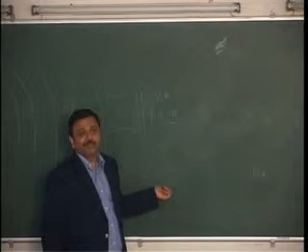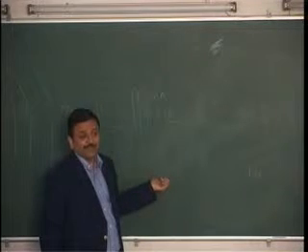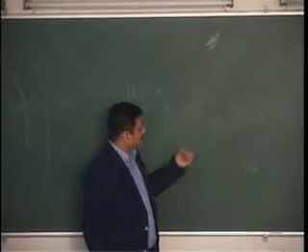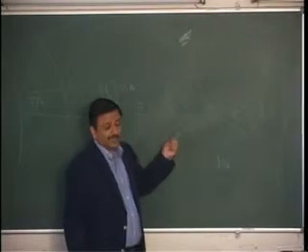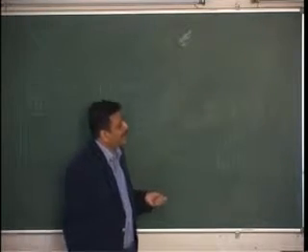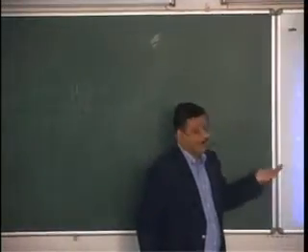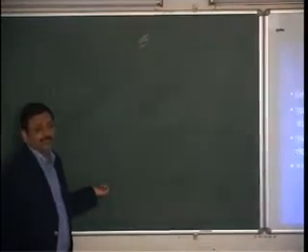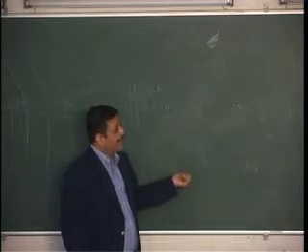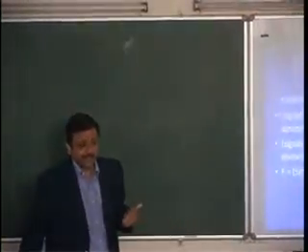The ground itself is picking up noise; we say nearly 300 Kelvin temperature is there over the ground itself. So you are in the microwave frequency. All the time when you take the G by T ratio, you take G as the gain of your antenna and T as the noise picked up by the antenna, which is nearly 300 Kelvin. So if you convert the 300 Kelvin into dB and subtract that from G, that's how you get the G by T ratio.